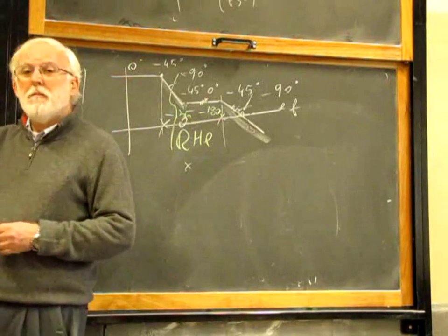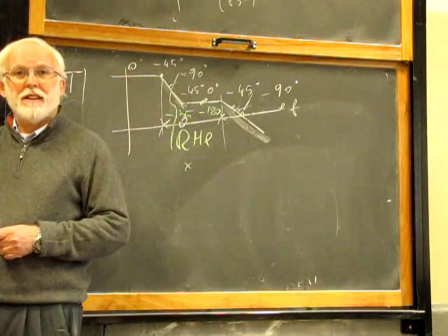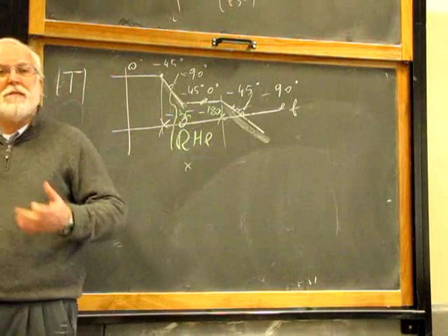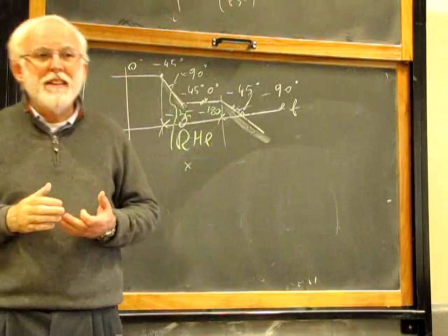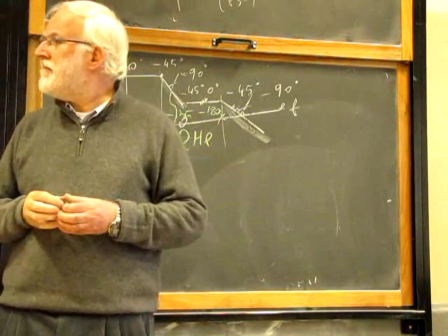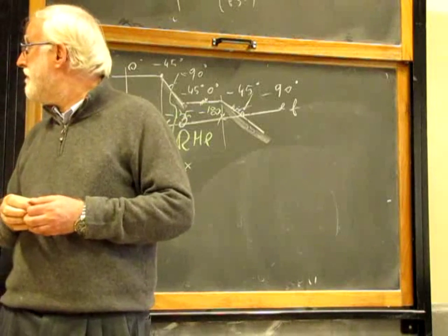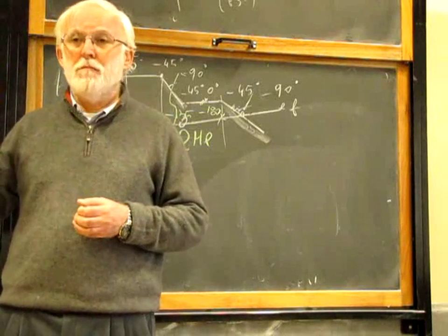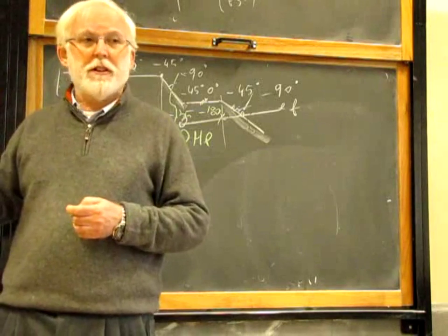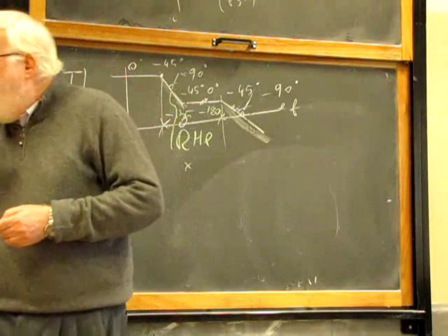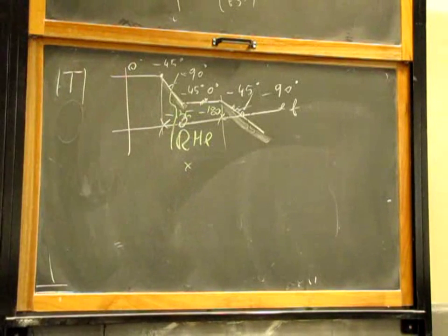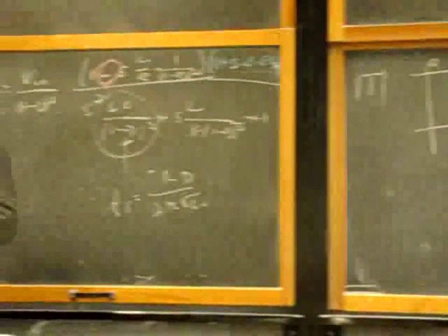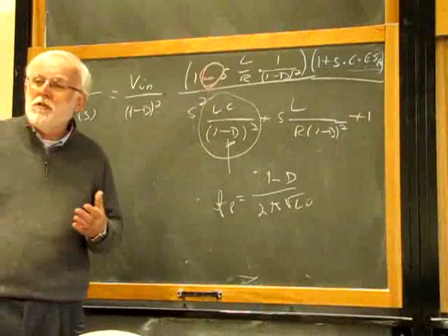We have to look for the minimum of this frequency and we have to cross over before it, because the right half-plane zero cannot be compensated. This happens also for a boost converter, for a buck-boost converter, for a flyback converter. In a flyback converter you can change the schematic and remove this right half-plane zero, but if it is there, you cannot compensate.